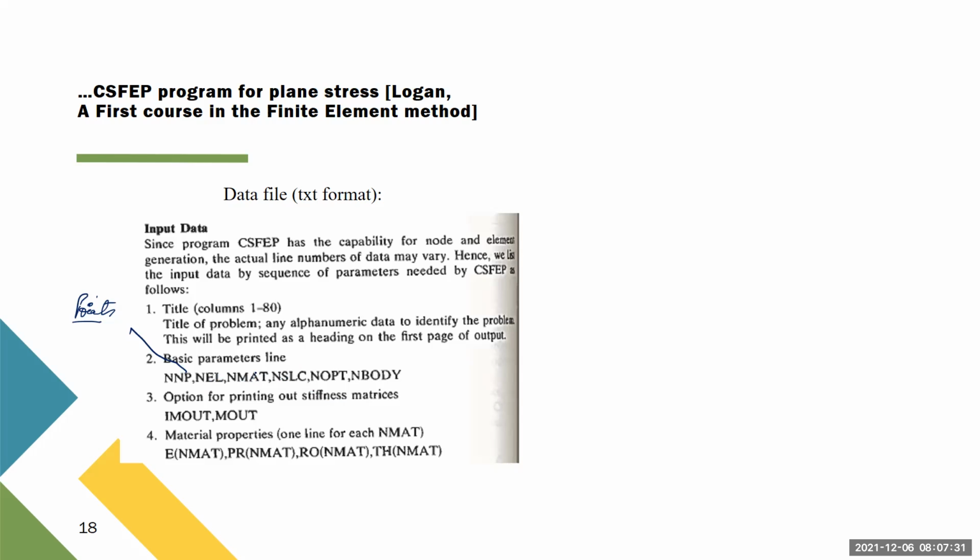See, for example, you could have a beam composed of two materials, so you could have this partition like this. But down here in these elements you have one Young modulus and one Poisson ratio, and a different one for the upper ones. So in that case, you could have more than one material.